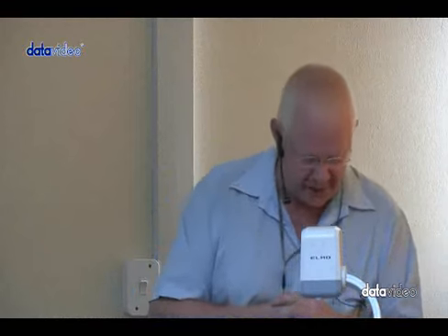All right, now in 6.3, you can see that these subscripts get changed for the different configurations of amplifiers. In the next section I will explain how to differentiate between the different configurations of amplifiers. But you will see there are only three. What is the clue? The transistor only has three terminals, so you can see it relates to the terminals. The names are common emitter, common base, common collector. Those are the three configurations, but I will show you in the next section how to differentiate between them.